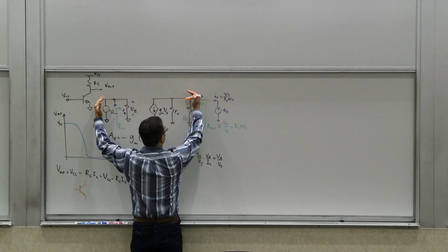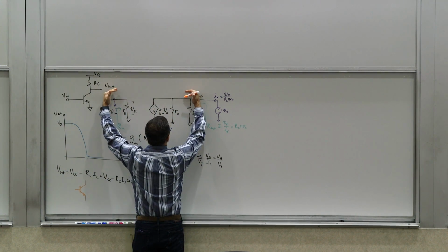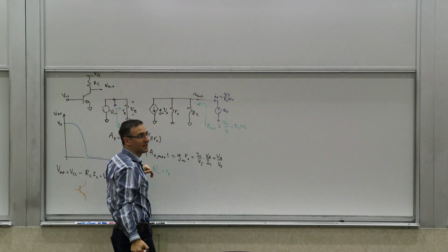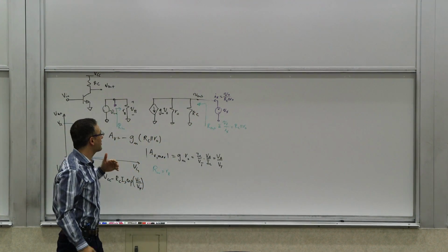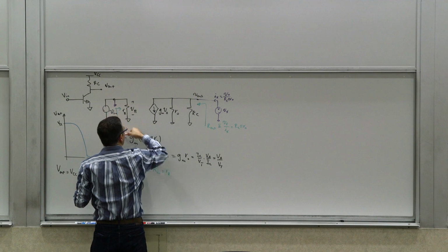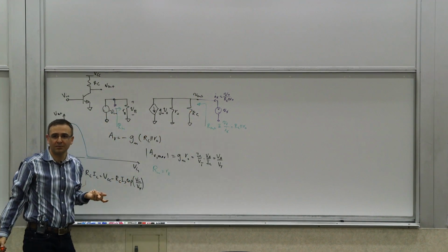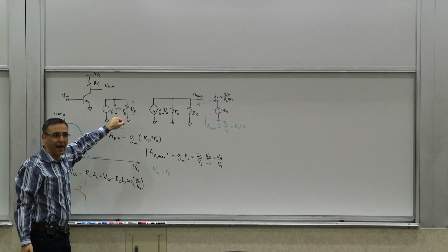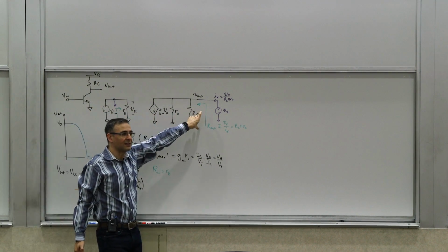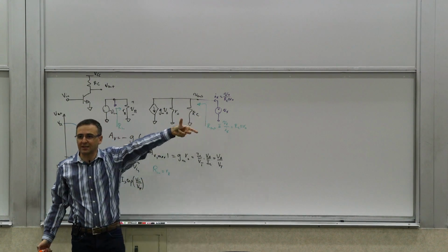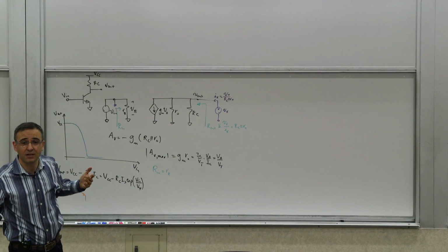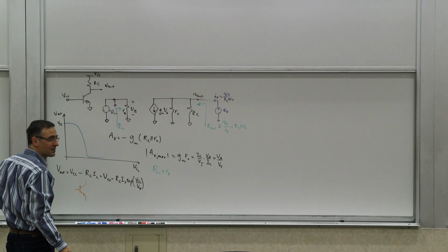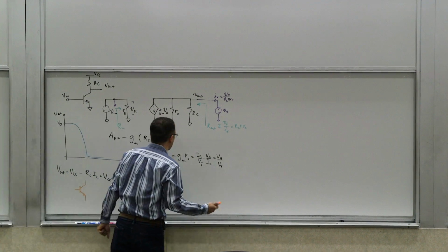When you look into it, think about this as a black box, right? And say, what is the Thevenin equivalent of this thing? The Thevenin resistance of that thing, how is this calculated? The Thevenin resistance of this entire thing. You null all the independent sources. We nulled this. And you determine what's the resistance that's seen, right? Or the Norton equivalent. That's how we calculate. So it's basically the Thevenin or the Norton equivalent of that box from a network circuit theory perspective.